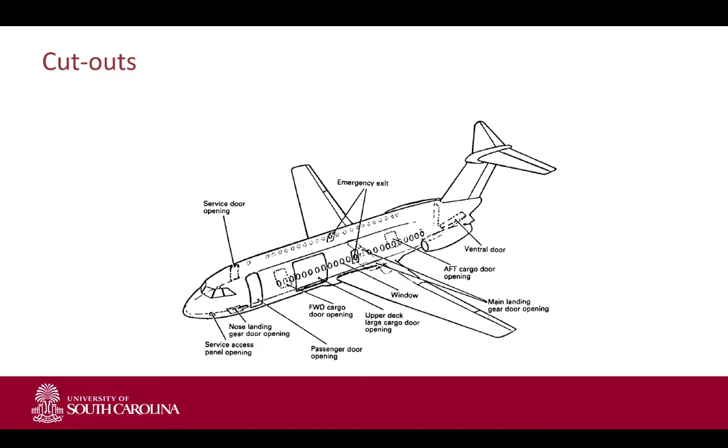Say, for example, what we see there is the door panel. Of course, when you take a door panel out, or a panel out, say an inspection hole, you will disturb the shear flows, and how do they get redistributed? And then if we have time, next week we'll talk about how to analyze a beam in a bit more detail than just looking at the panel cutout.